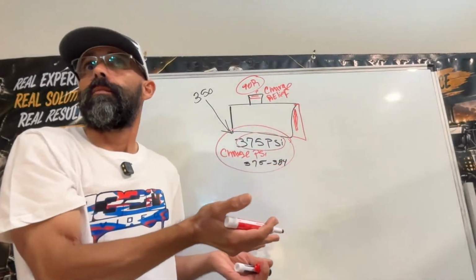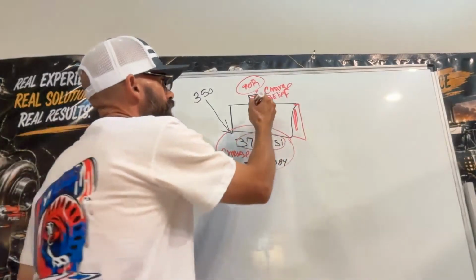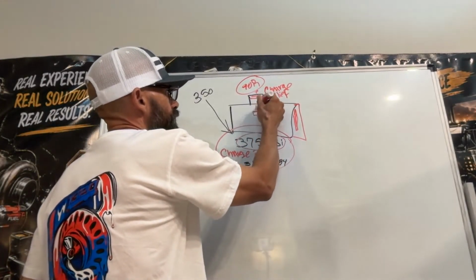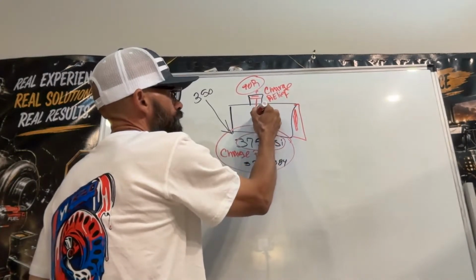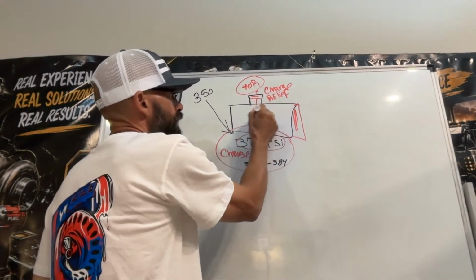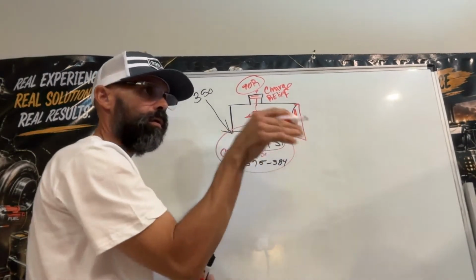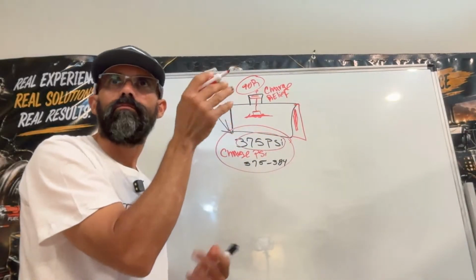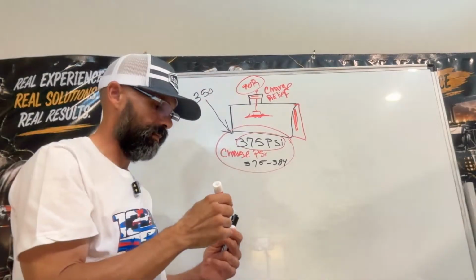I'm not saying that it's always, but it could be that the seat inside the pump for the relief valve is worn out, because oil goes through there, right? As oil goes through there, it causes friction and heat. They tend to wear out, right?